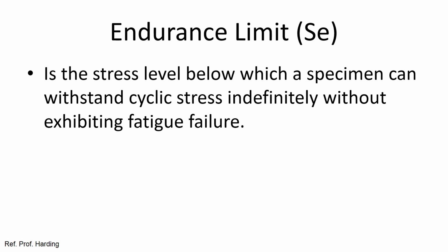Remember that these implants are subjected to cyclic loading. The teeth come together 4,000 to 5,000 times a day, so that's a lot of cyclic loading, and we have to make sure that we don't exceed this endurance limit, because if we do, we'll end up with fractured components.